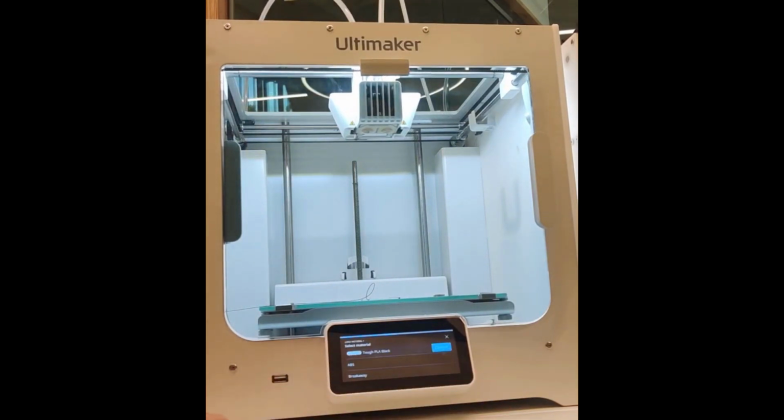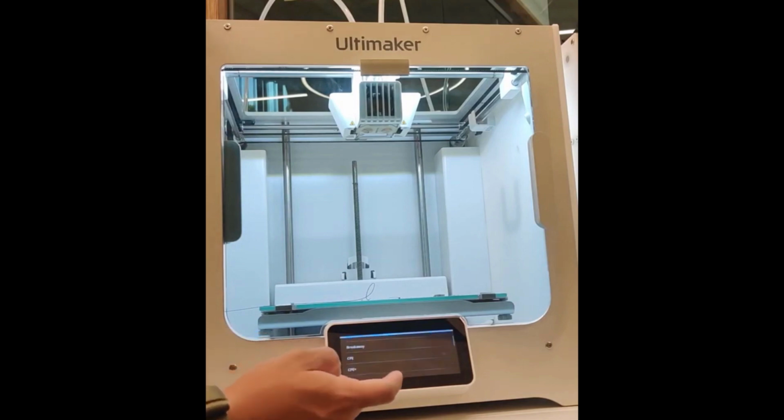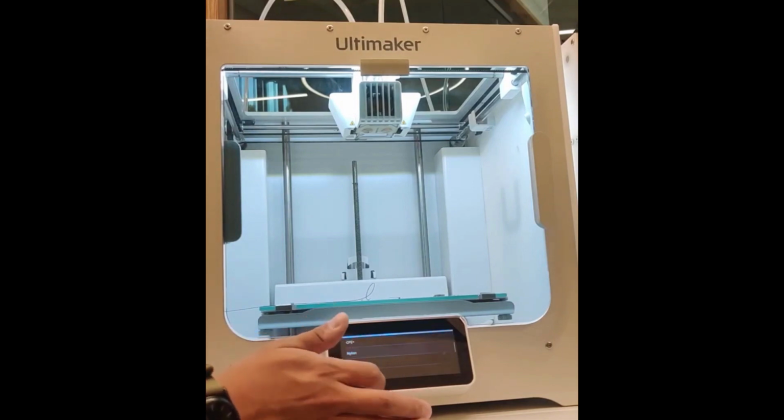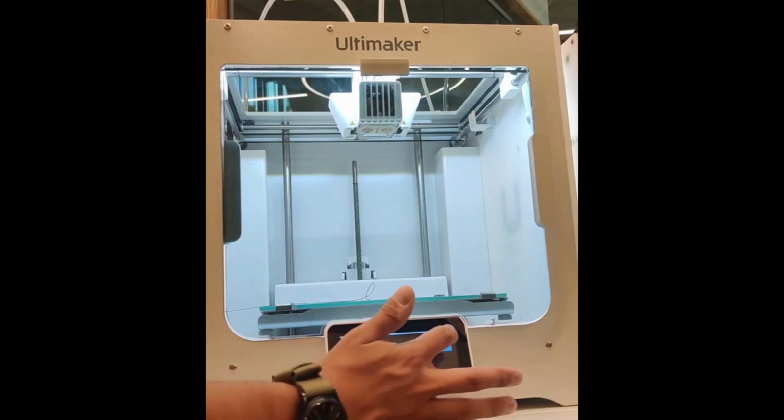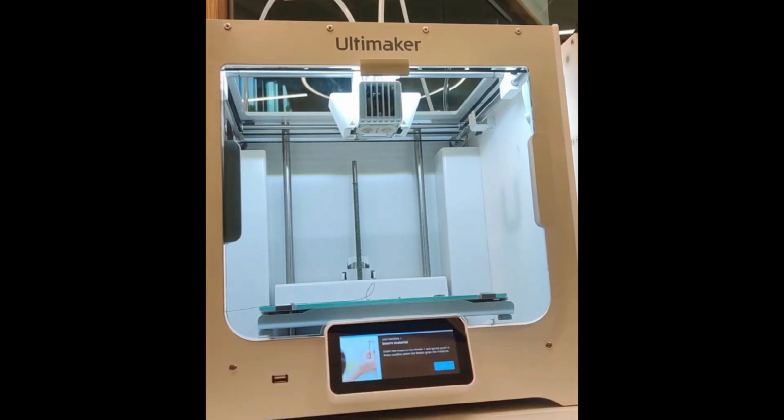And then this is where you select whatever material it is you're trying to put into Bay 1. Since it already has an NFC chip, it knows that it's tough black PLA. But for any other generic brand, you would have to scroll and click on whatever it is that you have. Again, I have the NFC chip, so I'll hit confirm here. It'll tell me to insert the material like I did through the little hole, snap the lever down, and hit confirm. And what we'll see is the head is going to warm up.